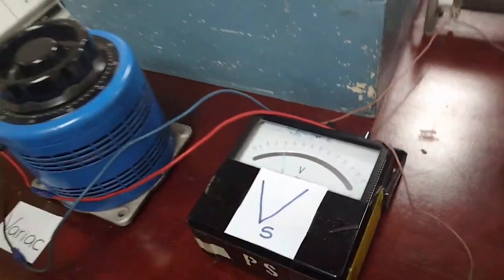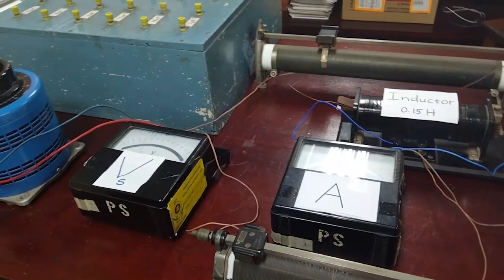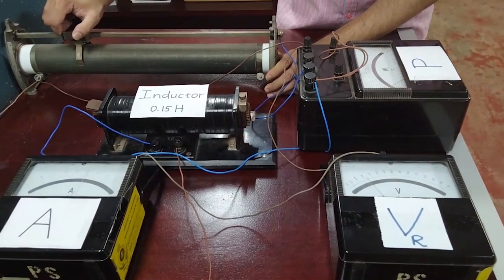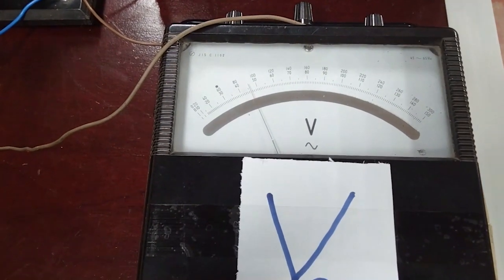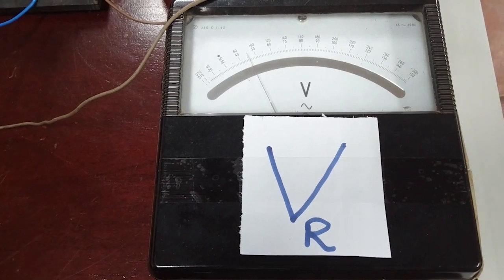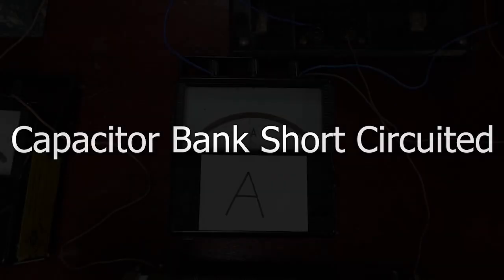Okay, after that, let's make our receiving end voltage to be 90 volts. So how can we do this? Simply change the load resistance until the receiving end voltage is 90 volts. Make sure to keep the sending end voltage at 100 volts and the receiving end voltage at 90 volts throughout this test. Okay, now let's short circuit the capacitors. That means we are not going to connect the capacitors here. Also, make sure to keep the receiving end voltage at 90 volts.